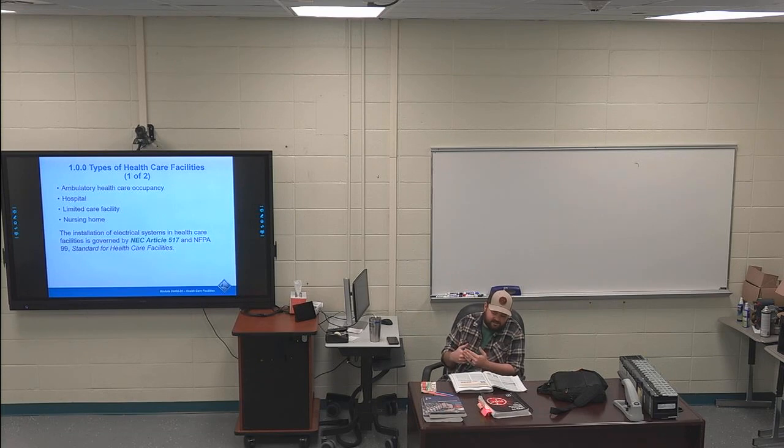The immediate next couple sentences are a separate highlight. The life safety branch and the critical branch consist of those items that are essential to patient care, out to the side, patient care spaces. So the life safety branch takes care of patient care spaces. The life safety branch supplies power to those items needed to ensure safety of the building occupants as well as patients.